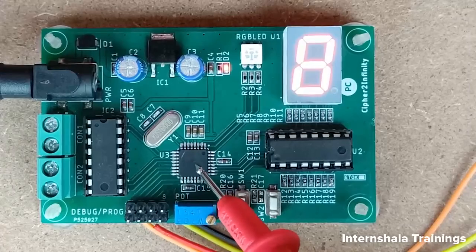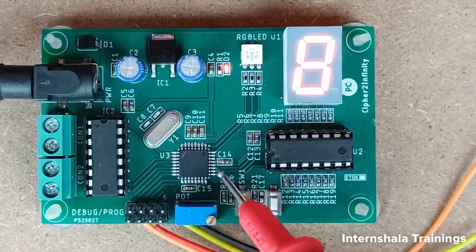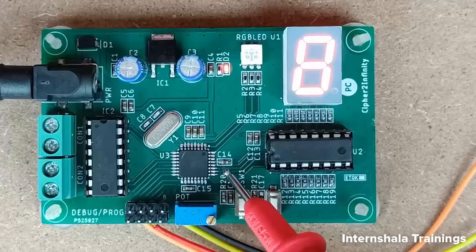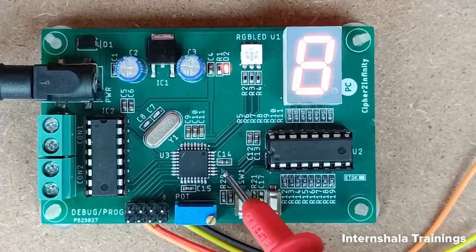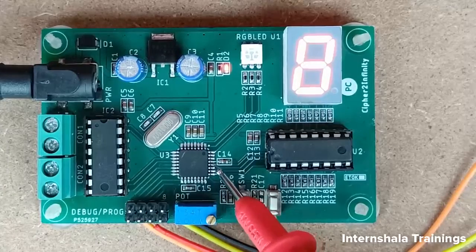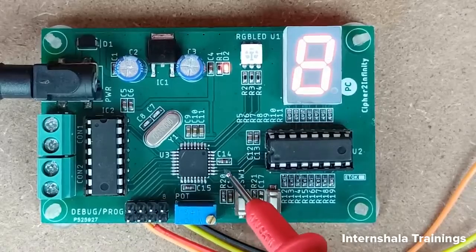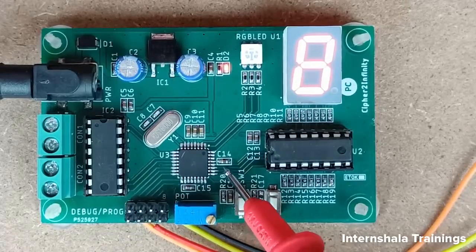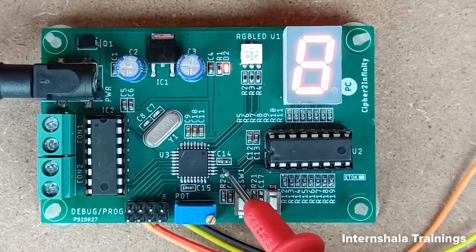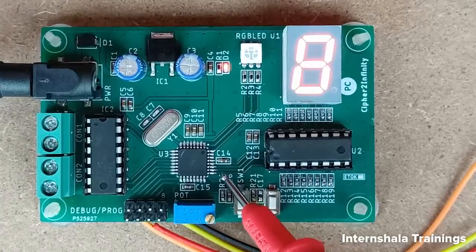Then the third point is, while programming the controller from the Arduino IDE, you may forget to connect this 0.1 microfarad capacitor on the reset line. I told you that we need to connect this 0.1 microfarad capacitor between the DTR pin and the reset pin. So sometimes it might happen that you forget this capacitor. Now that we have placed this capacitor on the PCB, many people connect this capacitor on the DTR pin external to the hardware.